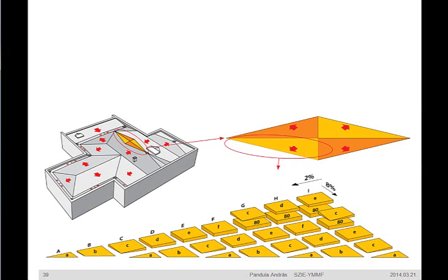To create such kind of sloping layer, we should design it properly in advance, and the heat insulation boards are arriving to the building site with marks, and a prepared consignation plan is required where to place these elements to create the adequate sloping layer.